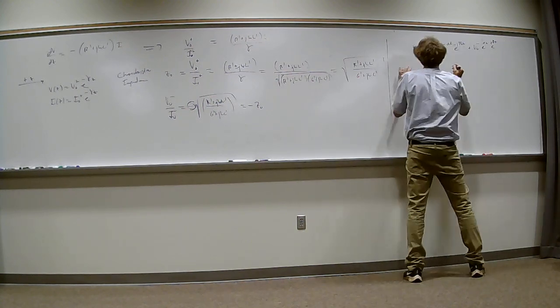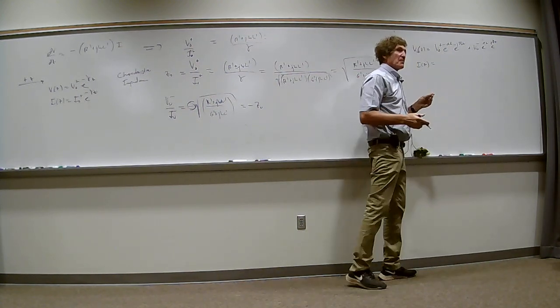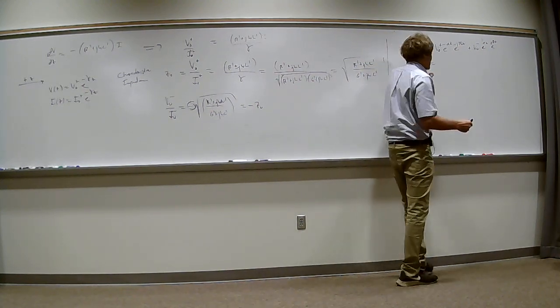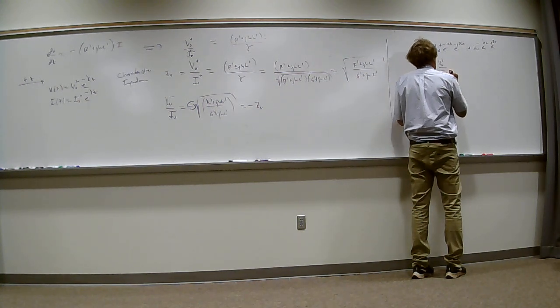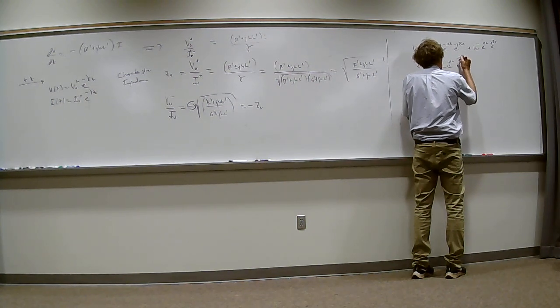This is in the phasor domain. And I can write I of z in terms of V0 and the characteristic impedance. Instead of putting the I0 there, I put V0 plus over Z naught times e to the minus alpha z, e to the minus j beta z.